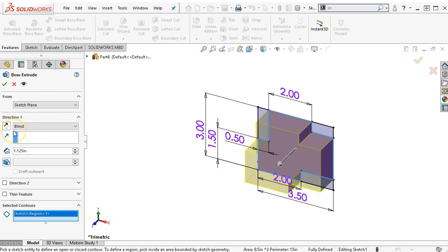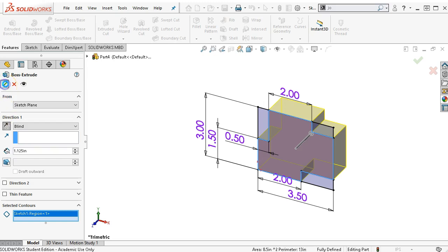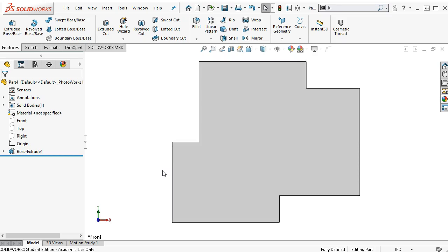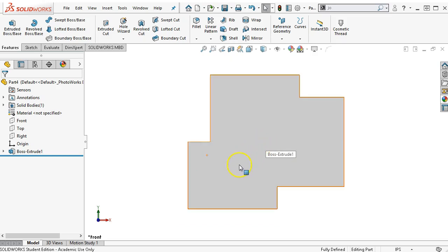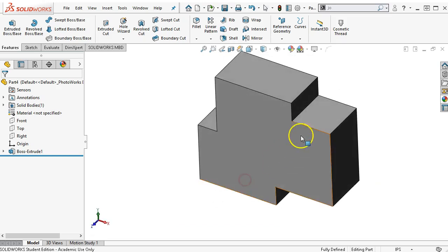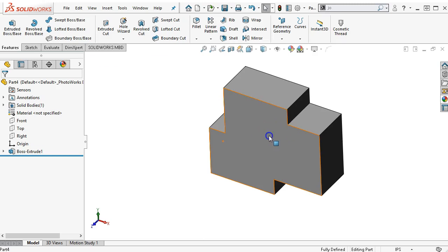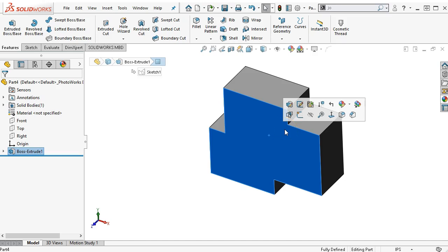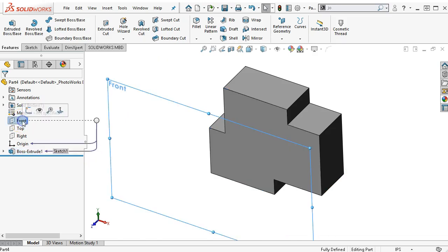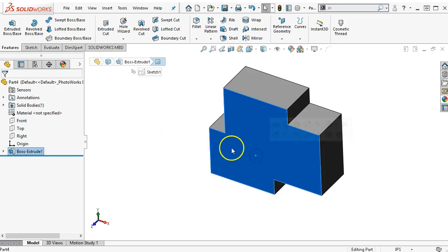Then my last decision is, does it come forward of the front plane or reverse the front plane? Doesn't really matter. We just need to pick. All right, so I did a Control-1 to bring it into view. Actually, let's rotate that out just a little bit so we can see if the orientation to the sketch works. So I've picked a face. If I were to put the new sketch on the front plane, that would be valid. If this was to move around, it may not have the same net effect. We would like the geometry to stay tied together.